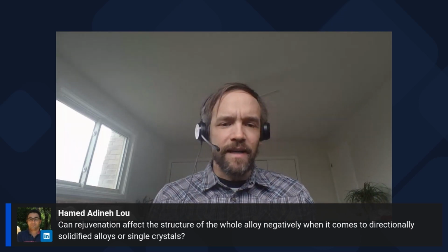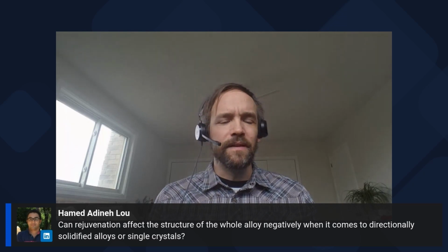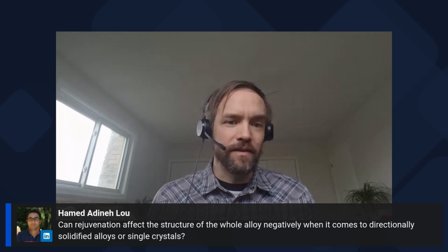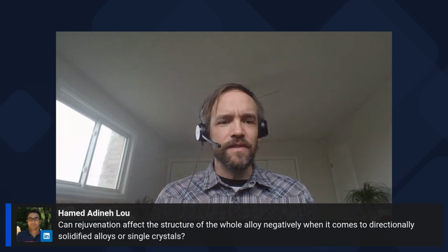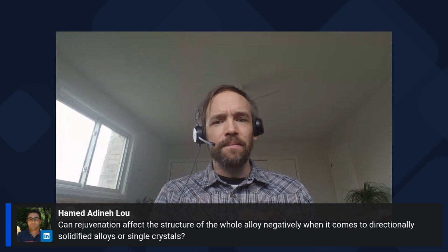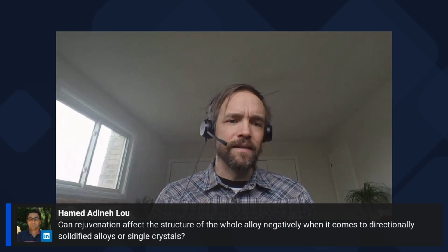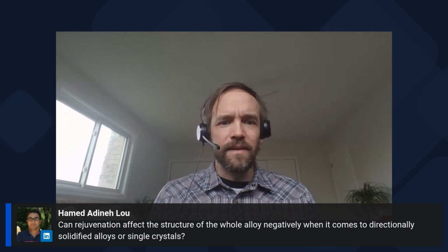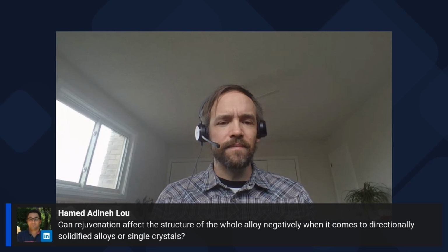With directionally solidified alloys, we don't have that same concern. The DS alloys are intended to have grain boundaries. They have grain boundary strengtheners, and so if there's a limited amount of recrystallization on the surfaces of the parts, then that's a tolerable state for those alloys. If it's more extensive, then it can be an issue, but we haven't encountered that as of yet. So for DS alloys, it's not really a limitation. For single crystals, there are some limits there.